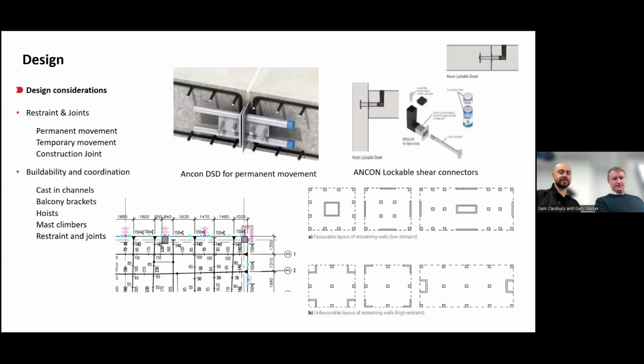Okay, and this touches on a bit more of what we saw with the restraint cracking. Yeah. So as we spoke about, we've shown this example below. You've got the top line of the GA drawings. You've got a favourable one, where you've got the stiff elements in the centre of the core, and you've got the stiff elements in one direction rather than in two directions. If you look at the bottom, where you've got stiff elements against each other in two directions, it's going to stop the slab wanting to shrink and move.